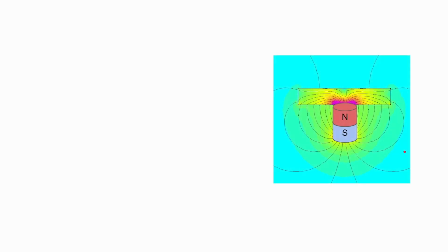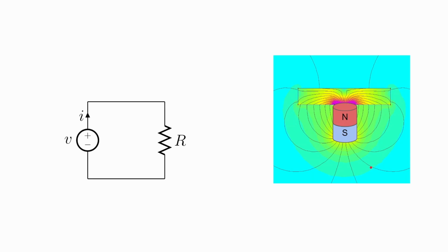However, magnetic calculations break down once you move away from simple cases. For example, if we were trying to calculate the flux for this system here, we need to find the air's resistance. The problem, though, is that resistance is proportional to cross-sectional area and length traveled through the material. So, what length do we use? This one? This one? Do we use an average of the two? The same goes for cross-sectional area.